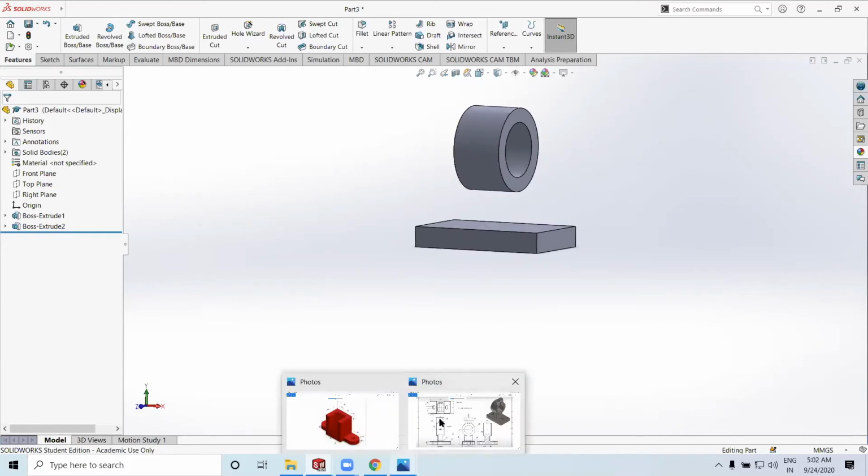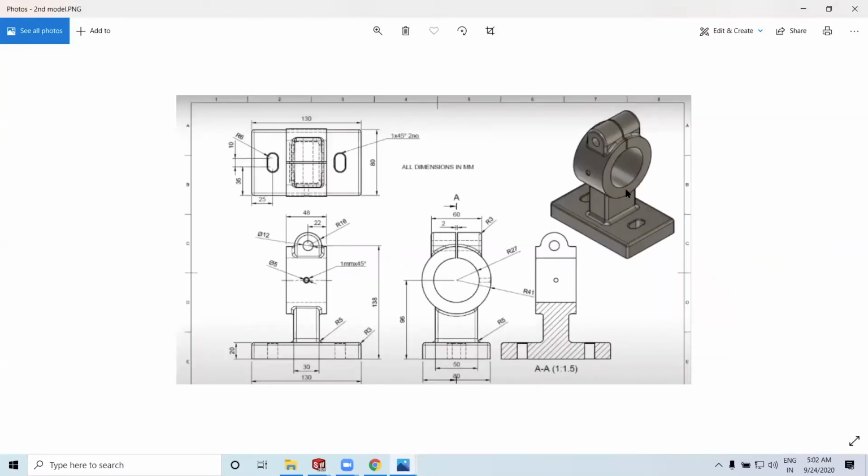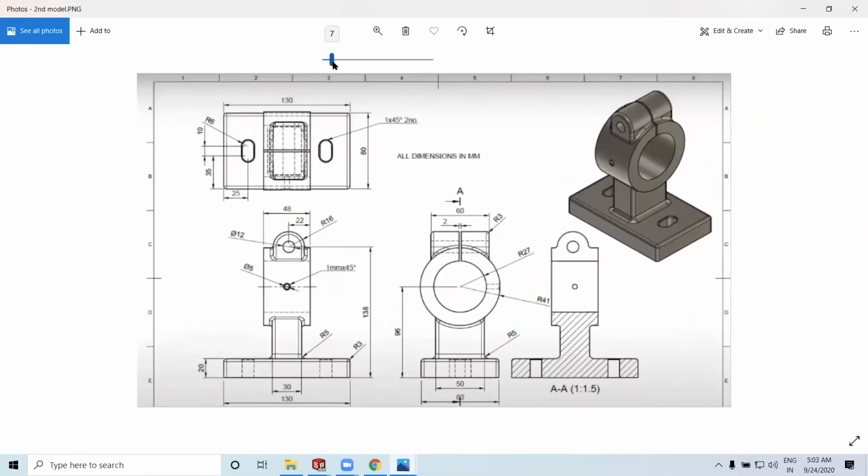Now, moving on to the next step, you see this rectangular support, which is actually supporting the concentric surface. It starts from just the top surface of the rectangular base. Now we need to get the dimensions of it. As you see from the side view, the width of this rectangle is 30 units. Now shift to your right and look at the front view. The total length is 50 units.